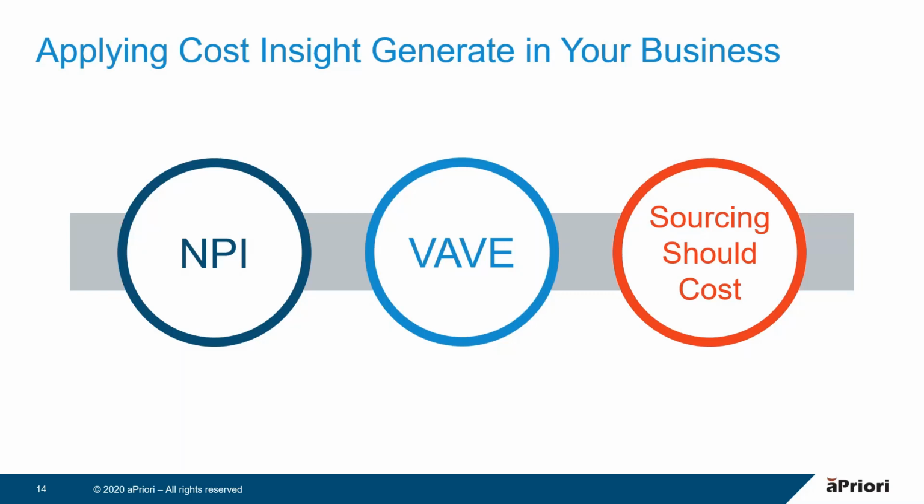What you want to start with is costing those parts so that you can perform a should cost versus known cost kind of analysis using reporting once they're costed, or look for outliers by looking at the DFM risk ratings to see which parts might benefit from a redesign, in the vein that Steve was showing earlier. Similarly, sourcing can also benefit from automated costing, supporting quote analysis and should cost negotiations with suppliers. You could take all the parts in a bid package, automatically cost them, and make them available for procurement personnel to use during their negotiations.